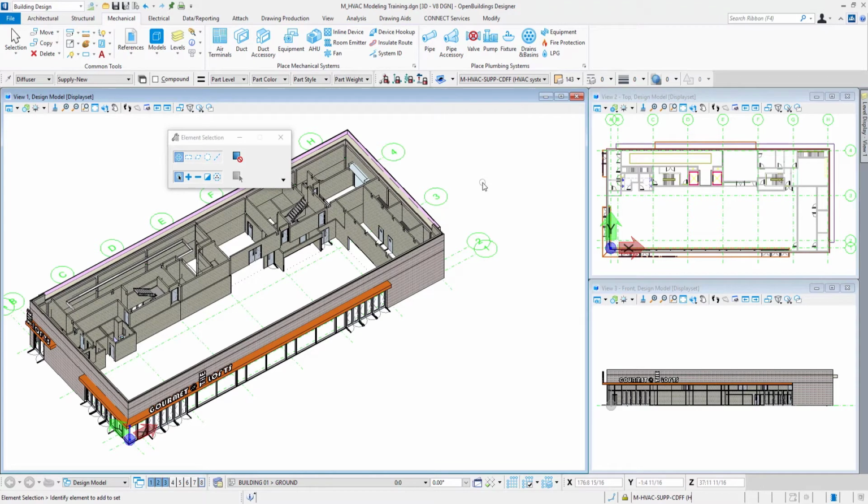Each type of diffuser is a catalog item with properties inherent to its type. Various configurations of air terminals can be modeled using the specific item's properties. When placing air terminals in the model, we have placement options available, including a base offset to locate the diffuser at a specific Z elevation within the model. And then we'll also see how the terminals have placement options for justification.